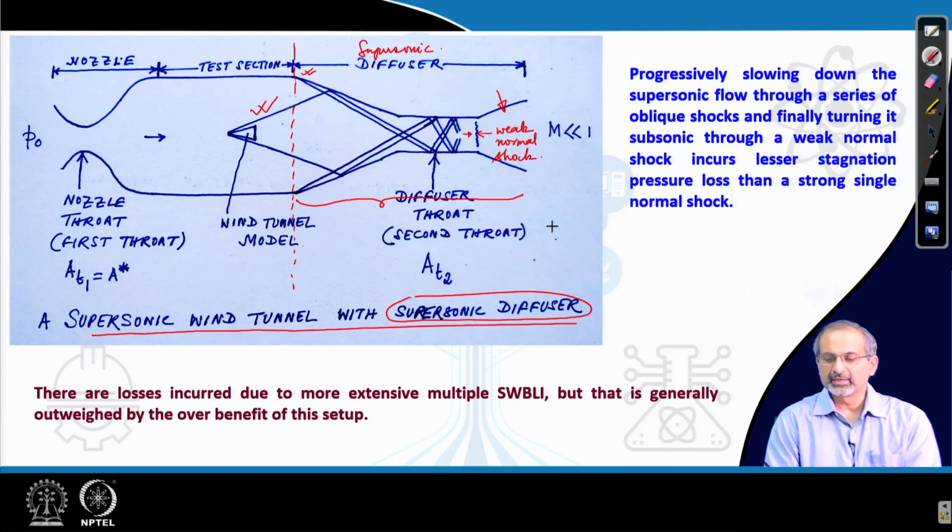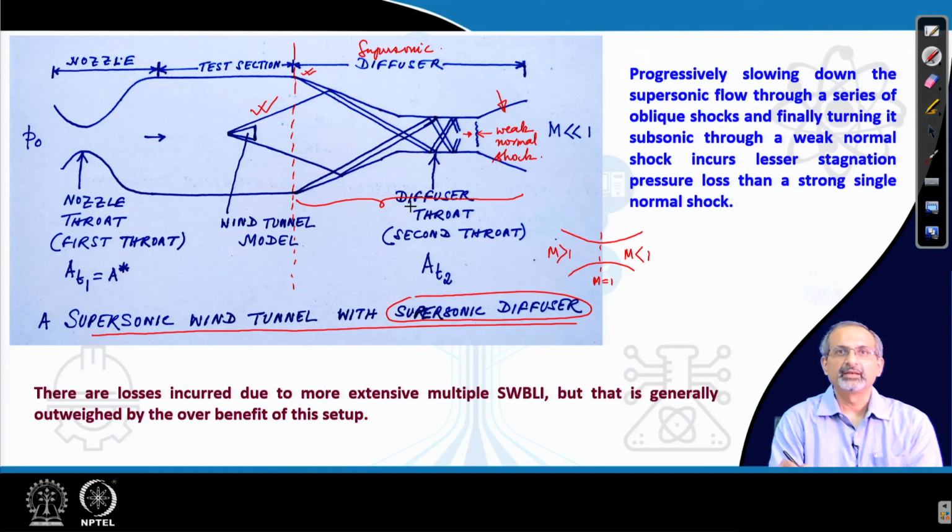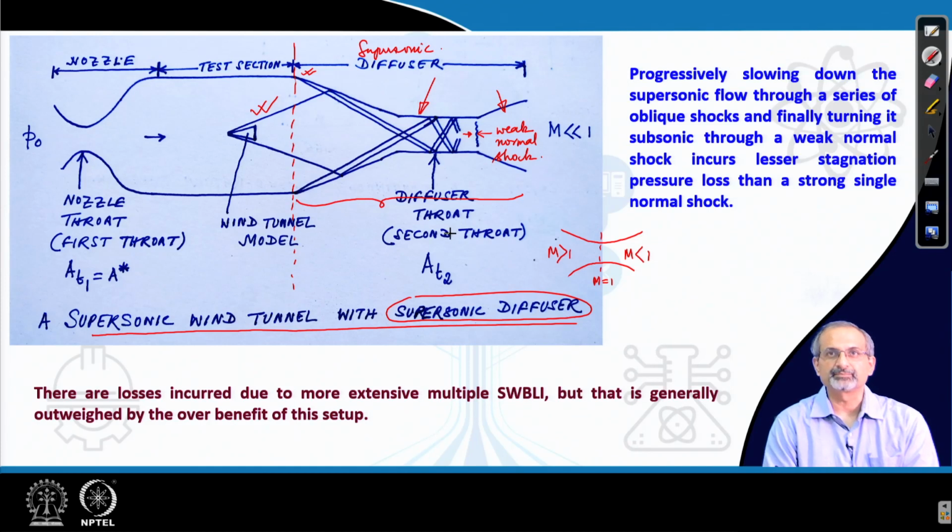If it was handling the flow in an ideal world, then what would have happened is that it would have taken a supersonic flow to a sonic one and then a subsonic one, but because of obvious irreversibilities and losses in real world flows, we do not have such a solution available, but this is the best possible in such a situation.